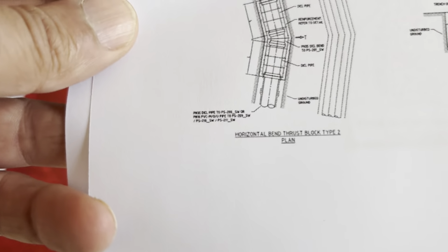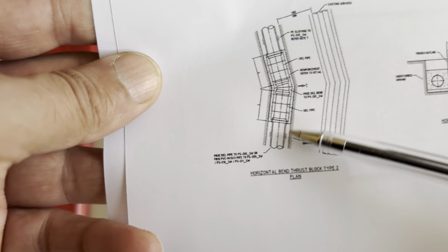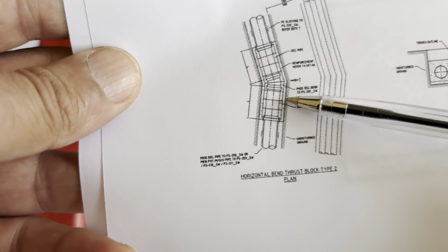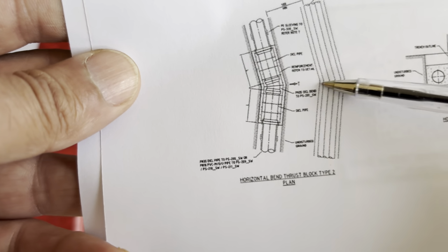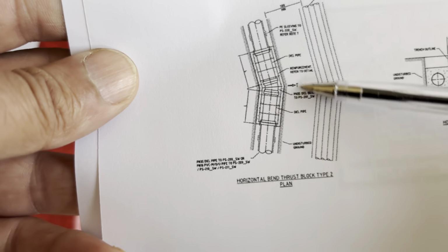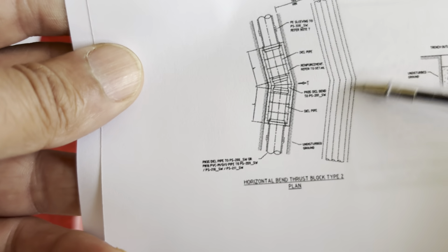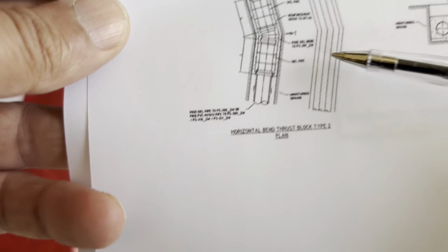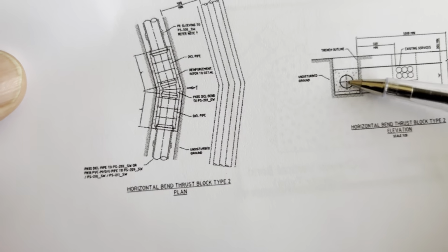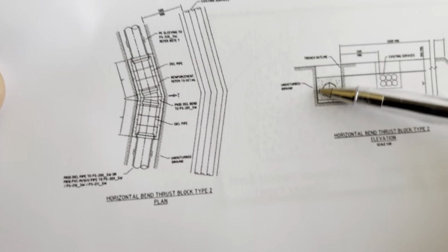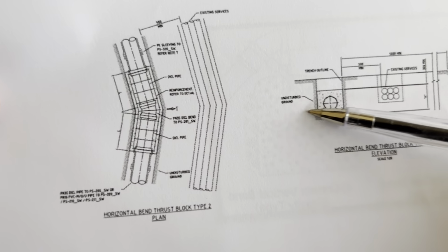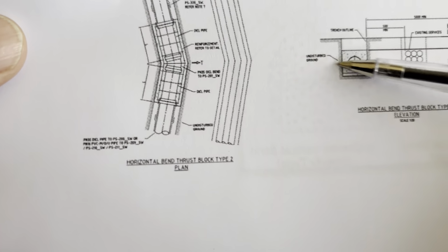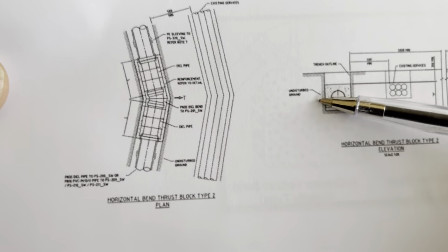And another part that is very popular in design is the plan view, and this one has a slight bend, and we have thrust load in this direction. So we need to have a concrete part here to take this load. If we have space, we just put a concrete block to transfer the load to the soil. Otherwise, we need to have some encasement that takes the load, but itself should be heavy enough to act with friction or interaction with the soil to take the load and stop the movement.